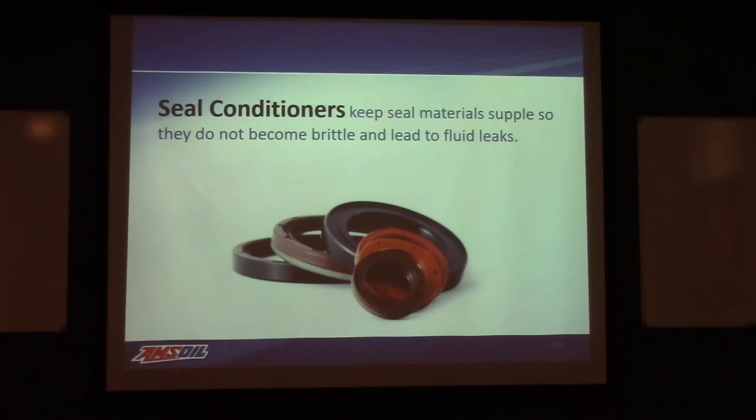Seal conditioners. Base materials react with the materials used in the production of seals differently. Some cause this material or these materials to swell, which is great, because what happens as the seal wears, its dimension is reduced. If the oil causes it to swell, that could make up for that loss in material. So maybe a little swelling's good.